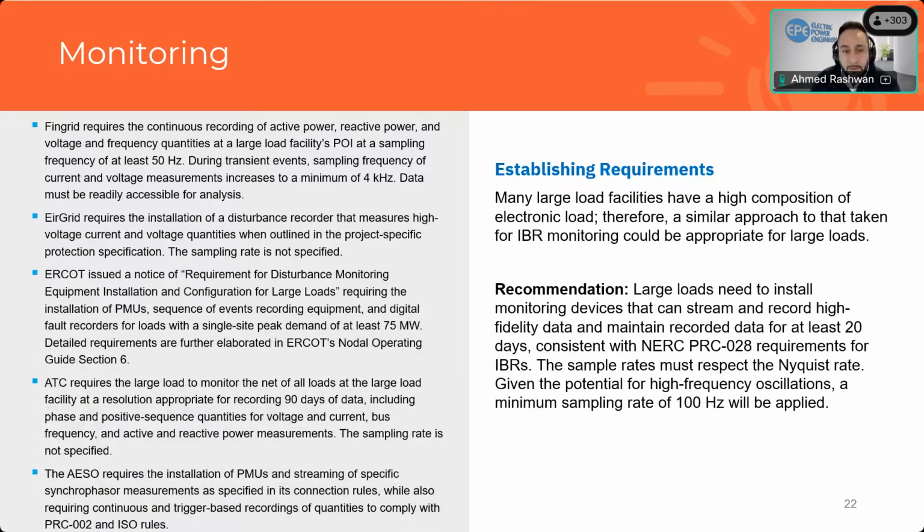I've included several requirements here that have been issued. I think in Europe they have some relatively well-established procedures around this. There's recording requirements. We've now seen in North America that there's now also streaming requirements for active monitoring in operations as well. And so, our perspective is install monitoring devices that can both stream and record high fidelity, high resolution data, and maintain the recordings for at least 20 days, consistent with PRC 28, and ensure the sample rate is reasonable to capture the phenomena that we're looking for. And in this case, we're recommending a minimum sample rate of 100 hertz.